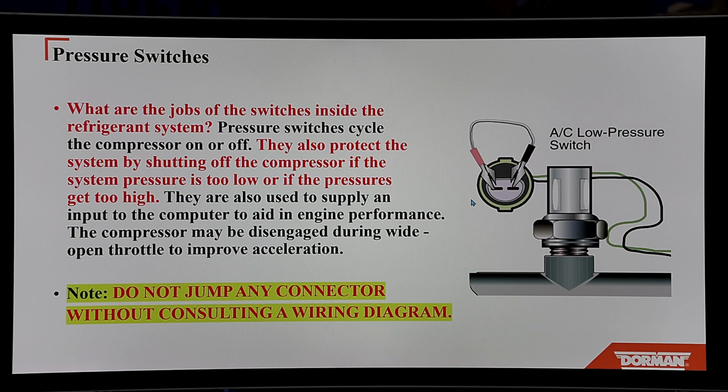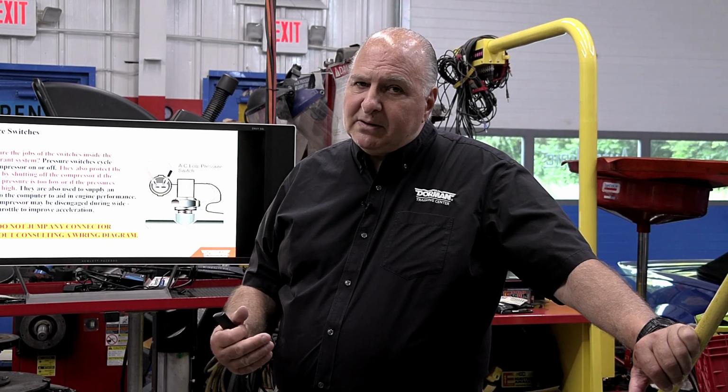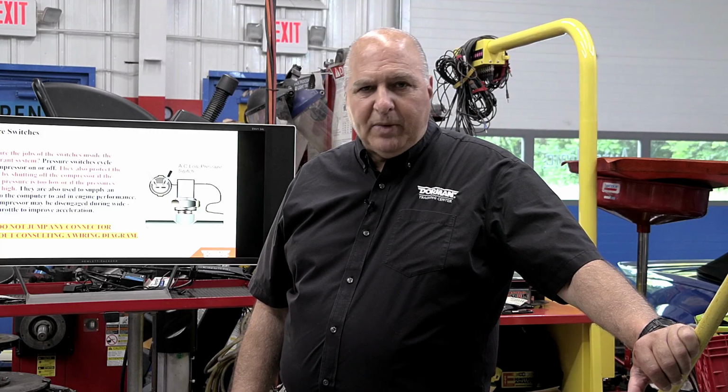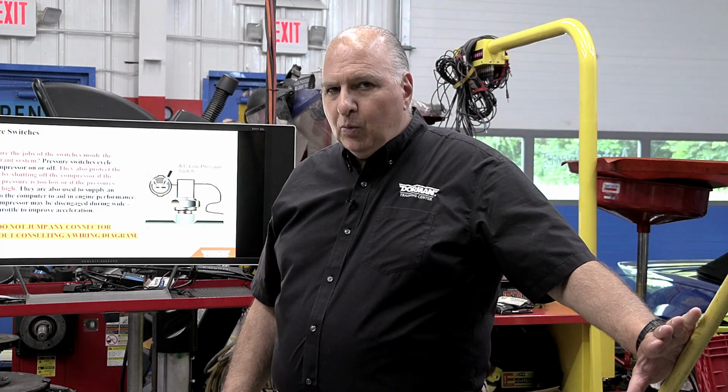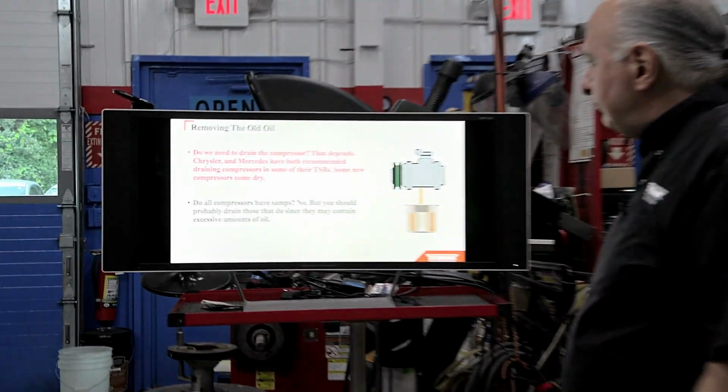Do not jump any connector without consulting a wiring diagram. Why? Because everything is run by a computer. And if you do something wrong, guess what's going to happen? You got it. You're going to have a problem, burn something up, and you're not going to be happy. So make sure you don't jump anything without consulting a wiring diagram.